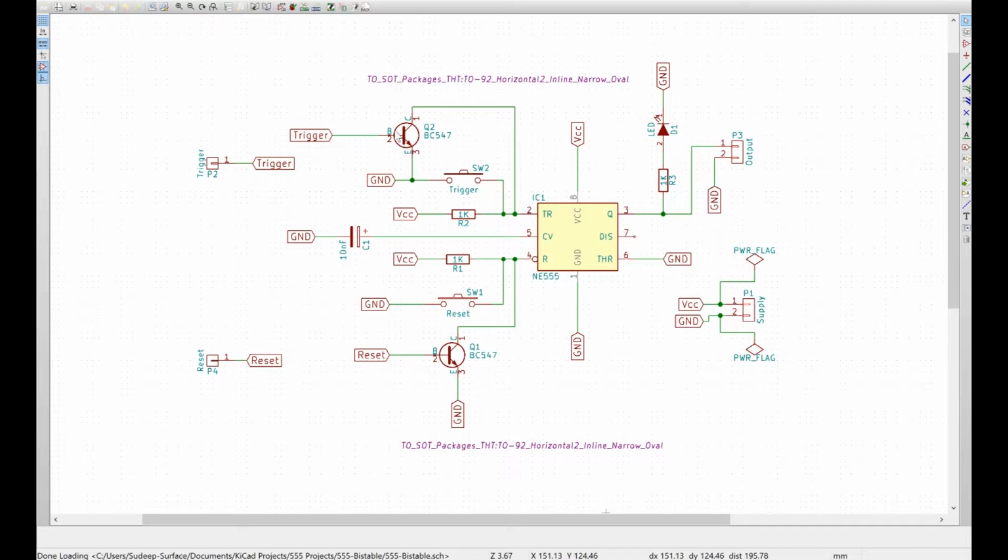So in either case, even if we are giving the trigger input over here as high, switching on the transistor, or pressing the button, what we are doing is bringing the trigger to 0 volts, which was otherwise at plus VCC volts. In this case, we would be considering that as plus 5 volts.